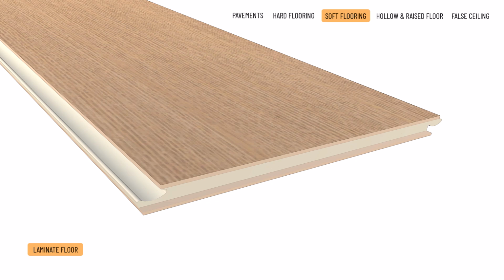Laminate floorboards are multi-layered structures with a high-strength HDF core layer providing the base. On the underside, a leveling or rigid melamine resin sound-damping layer is bonded to the core. On the top, an impregnated UV-resistant, colour-fast decorative layer is protected by a wear and scratch-resistant melamine resin protective layer.